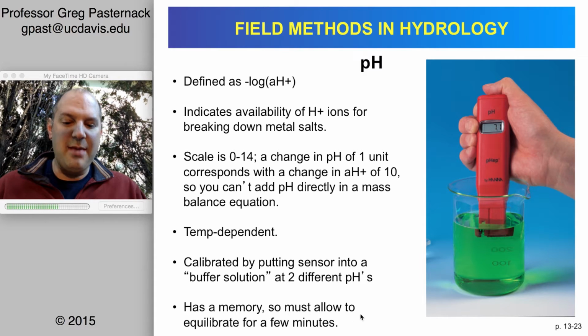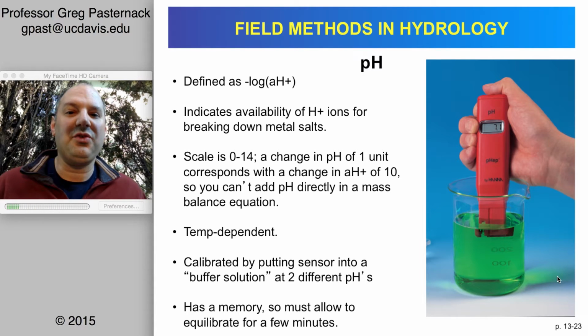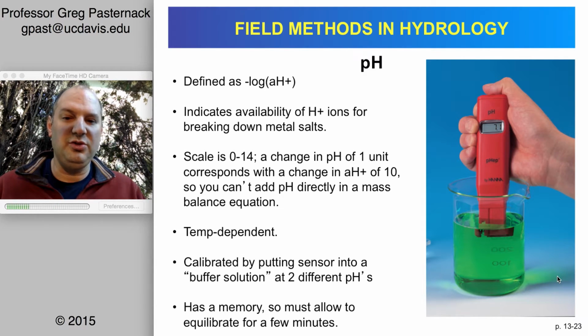But this idea about a memory, I'm not talking about the computer. It's like, you've passed ions through into the sensor, so you need to flush those out if you're going to go to a significantly lower concentration solution next.